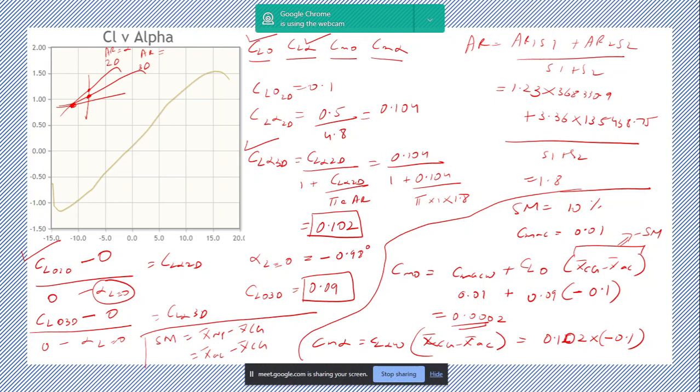So is the aircraft stable or unstable? Not 0.002? It is 0.001. Cm alpha is, okay, so is the aircraft stable or unstable? Stable, yes, because your Cm alpha is negative. You don't require any other thing to characterize longitudinal stability. You can also see that the static margin is positive, so yes, it has to be stable.